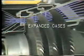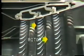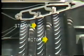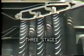It is in the turbine section where power is finally produced. The expanded gases from the combustor turn the fan-like blades of the turbine, producing rotary power. The turbine has some features like the compressor. Rows of rotating blades, or rotors, are attached to a central shaft, while stationary blades are attached to the outer housing.